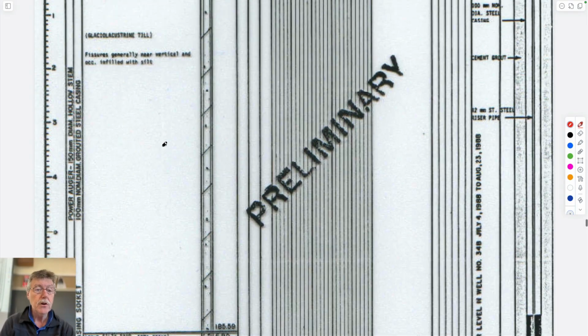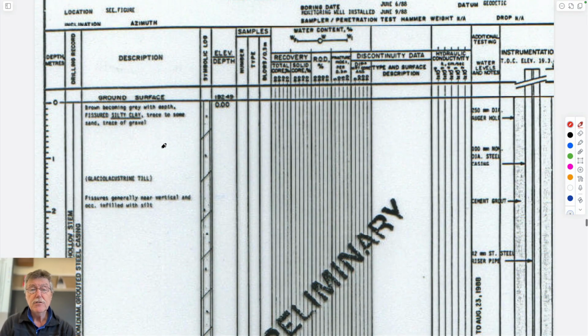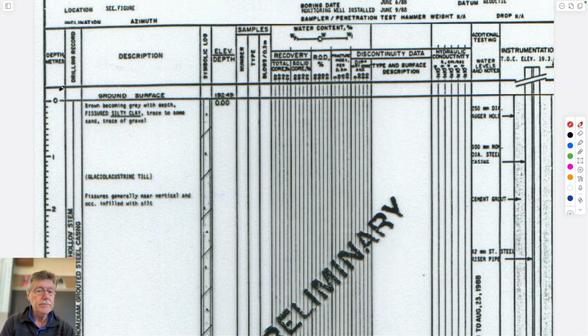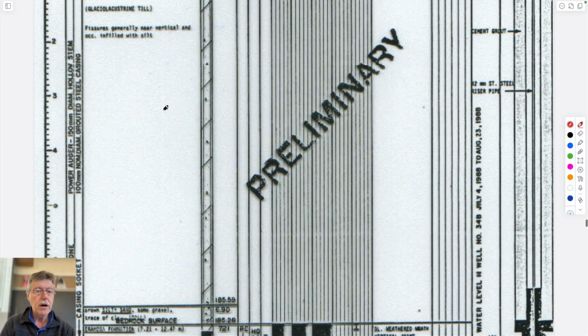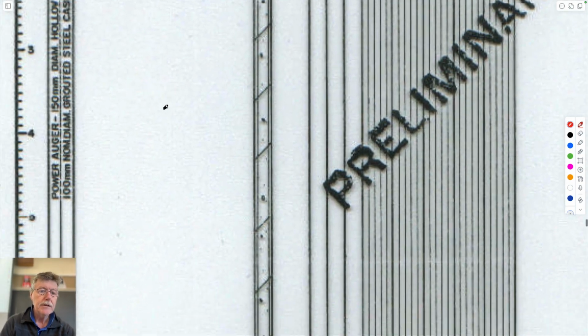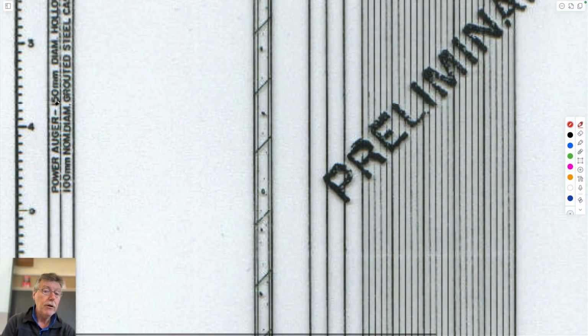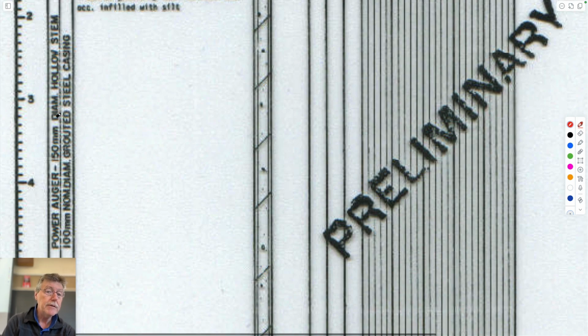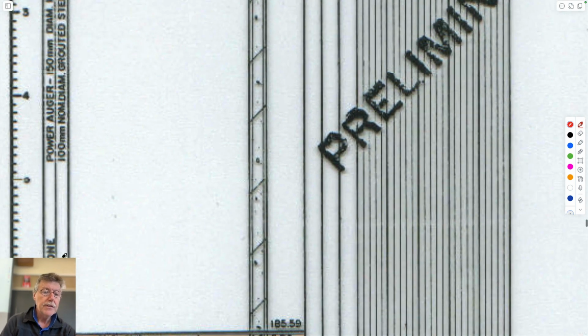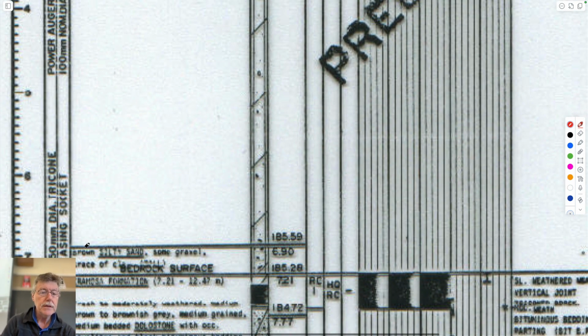And it would maintain all the information you want to know about the site. So a lot gets put on here. So this obviously is a log, so it's with depth. Ground surface here, as you could imagine. In this leftmost column, along with the depth, the method of drilling: power auger, 150 millimeter diameter hollow stem auger. That goes down to the rock head level.